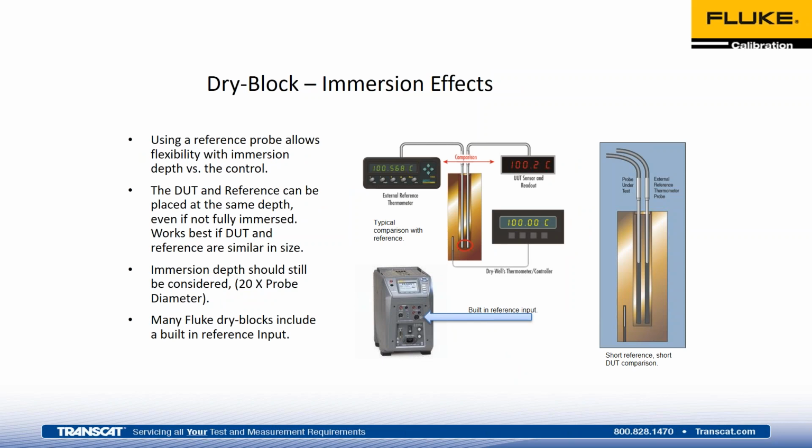So again, with the immersion effect, you can see here I've got an example of using a dry well with a reference. So we've got a device under test, a reference, and then our dry well's display. This is a really good way to do things where your probe or device under test is not long enough, or it's got a different size, or you've got a sizing constraint that causes you not to be able to fully immerse the probe.